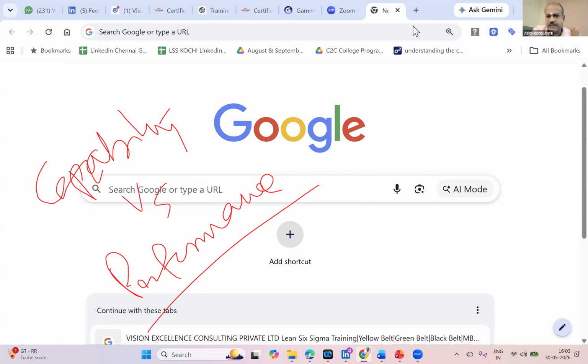And 1.67 and 2, there is no limit. It's only an industry guideline, AIAG guideline, which demands 1.67 for critical characteristics. You want to make it 2, most welcome. You want to make it 3, it's up to you. When the CPK is 2, that is called the Six Sigma capability. I hope all of you are already aware of it, right? When CPK becomes 2, then your Sigma level will be 6. Very good.